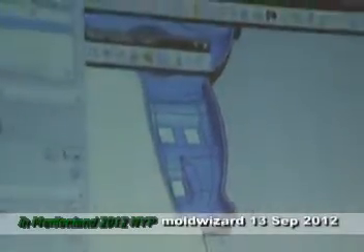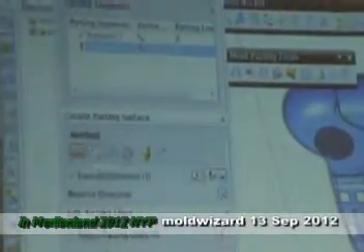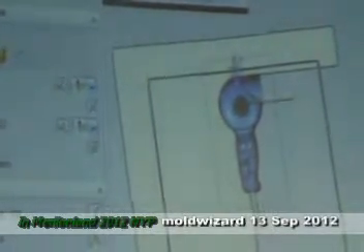Then we jump to the next segment. You can use extrude, or a sweep, or the planar bounded plane, or a large face, up to you. Here I still want to use the bounded plane because this is a 2D curve. Same method, I just cover up the whole block. It can be bigger, but actually now it's already enough. Then apply.